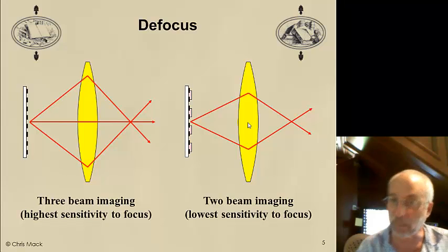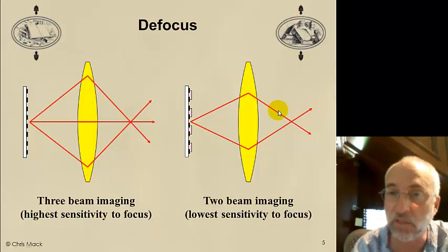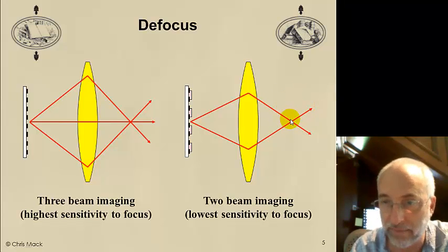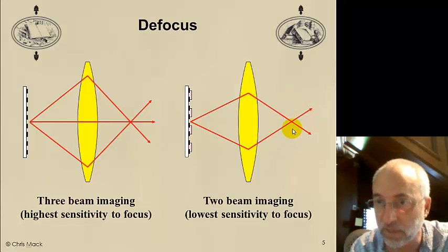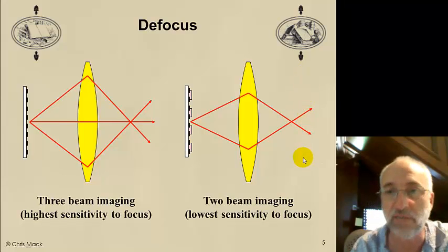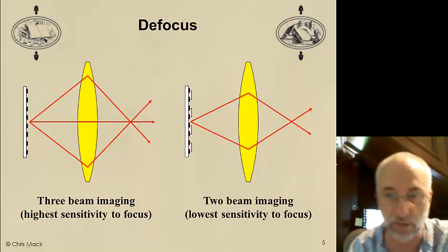What does that mean? It means when I look at these two rays arriving in focus, that is, in phase when they combine at the wafer, and now I move the wafer to be out of focus, well, look, both of these rays travel the same distance to get to the new wafer location.